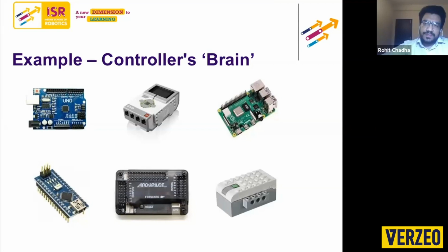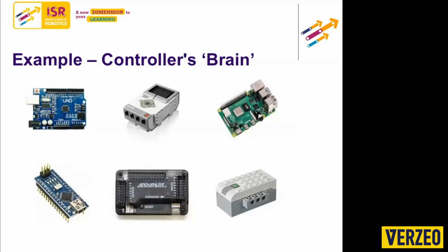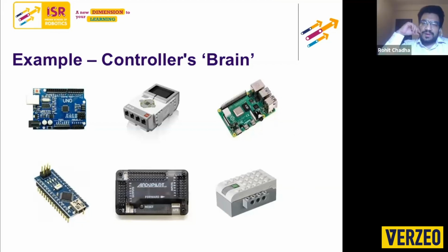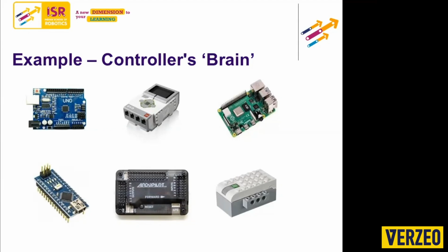Raspberry Pi can be connected to PC using your HDMI cable. Okay, if Bluetooth or Wi-Fi is available? Yes, you can connect via Bluetooth. For that you need to buy HC05, which is a Bluetooth device. I don't know whether the latest Raspberry Pi model has inbuilt Bluetooth. If your Raspberry Pi doesn't have inbuilt Bluetooth, then you can buy a Bluetooth device separately and connect using that. Okay, thank you, sir.